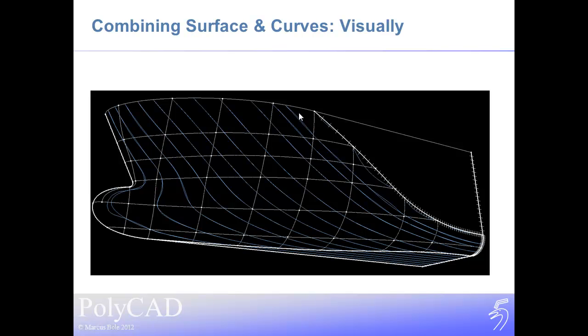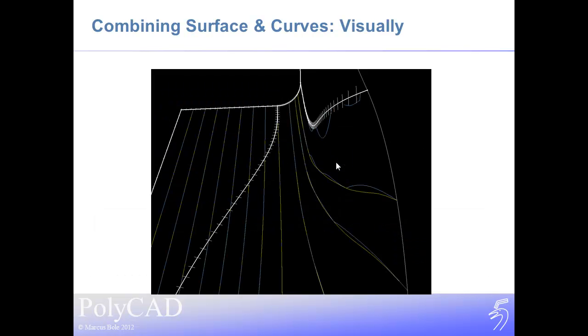Now these aren't the most obvious discrepancies that are coming out. They're definitely around the bow, but we can see a buttock coming out on the surface here, illustrating that we haven't developed these curves so they have the best tangent into the flat of side curve. We can see in more detail here with these yellow curves. The yellow curves are coming from the curve lofting, and the bluish curves are coming from our surfaces. And we can see that our surfaces are bouncing around, whereas our lofted curves are quite smooth. And both these outputs are generated from the same loft curves.